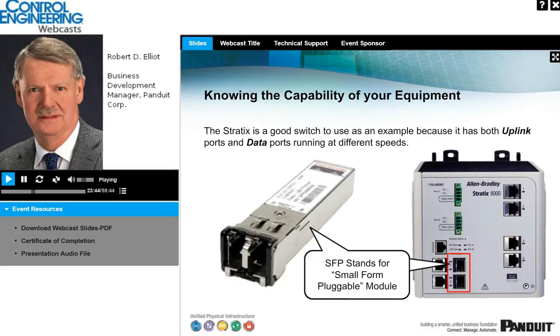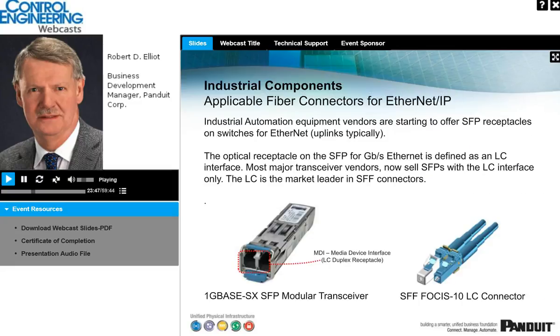That's an example of what the SFP module looks like. And then you can see here on the rear end of the modular transceiver, this shows the very commonplace now so-called LC connector interface. On the right-hand side, you can see this dual connector type here, LC. The 2 ports are spaced about 6 millimeters apart, and there are many other fiber connectors available, but these are most commonly used in this kind of environment.